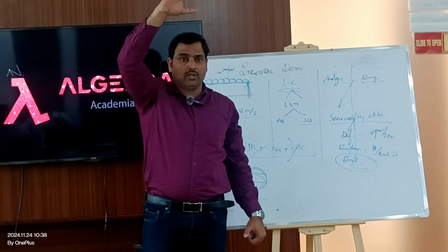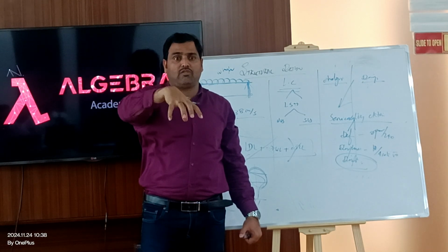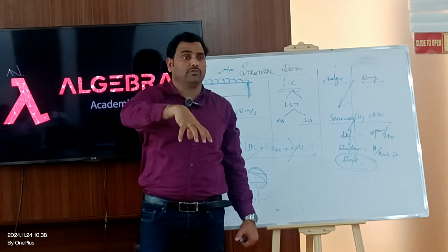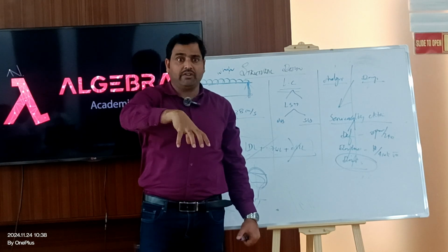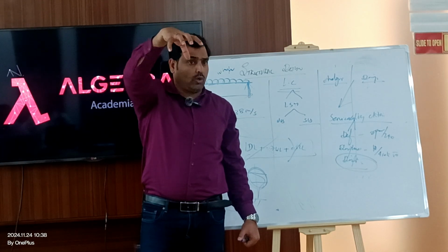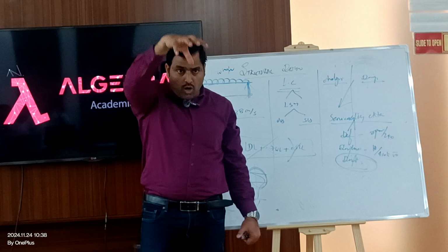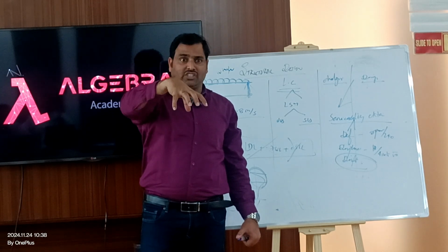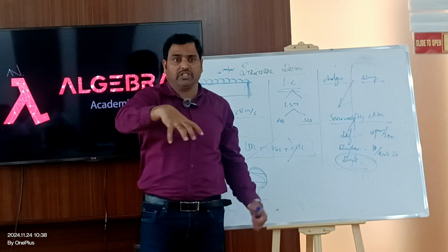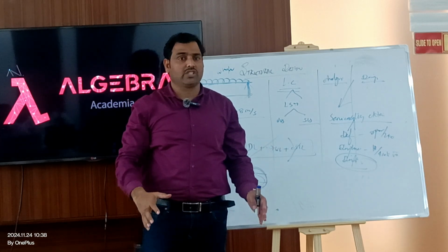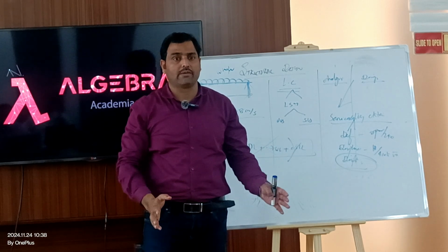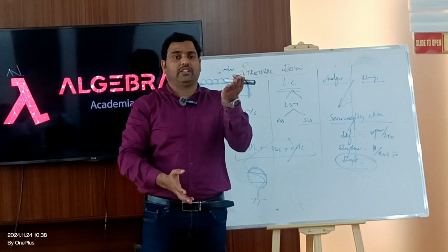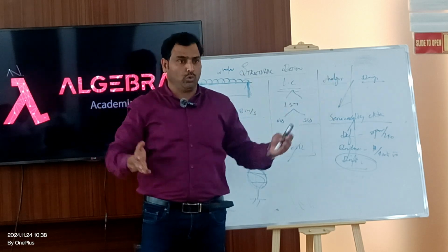I can provide it. But the problem in seismic is that the lack of stiffness will govern the majority of the floors. In between might be 8 floors, 10 floors, 12 floors, 15 floors. For the whole 15 floors, you cannot give the stiffness as it is. Maybe suddenly in between the columns, you cannot increase it. Might be the column size comes 300 by 800 or 400 by 1 meter. I cannot go from the 10th floor onwards 500 by 1.2 meters.